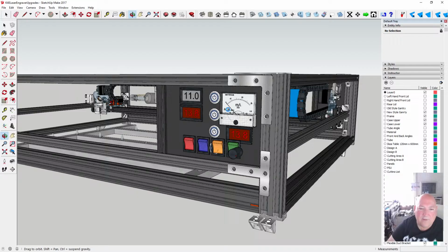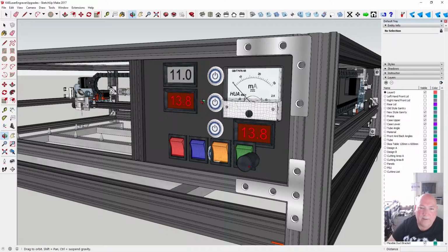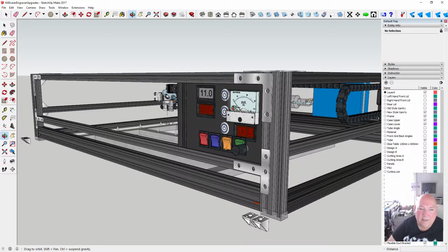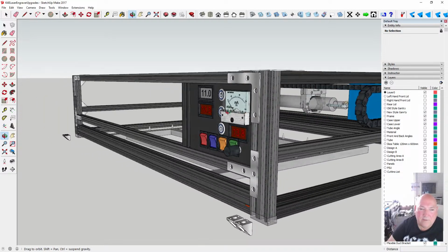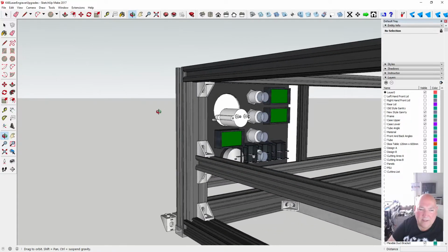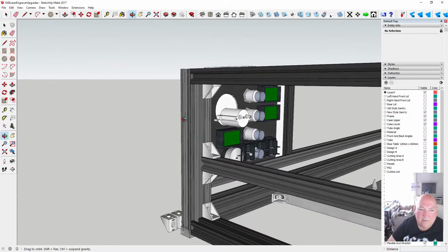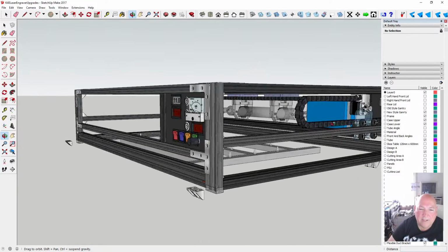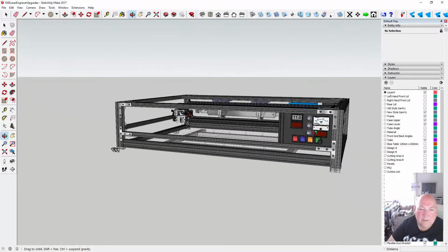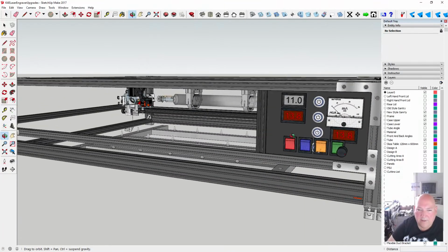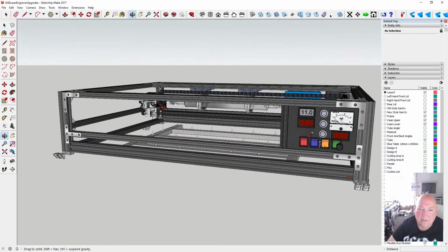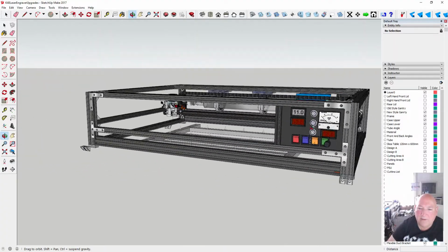Because all this is auxiliary stuff. All this here, it's auxiliary. You don't need any of it, as far as I can tell. I've got to look into that a bit more, but as far as I can see, you don't need any of that to get it to run. It's all done in the software now. The old buttons on the old K40 and display, there's no way to use them as far as I can see, so you don't use that.